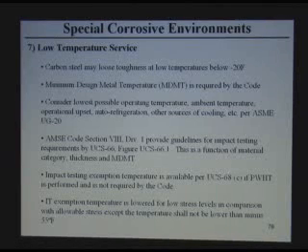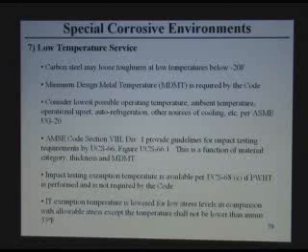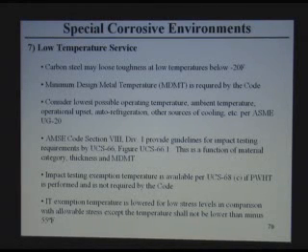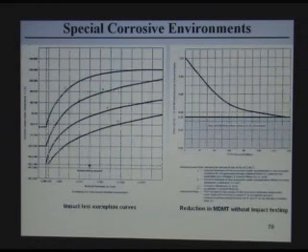If you would like to avoid impact testing, you can heat treat, if it is not required by code. So that will allow you to use the material without impact testing. And if you're working with very low stress levels in the components, you can still lower your minimum design temperature. You can work with non-impact tested materials.